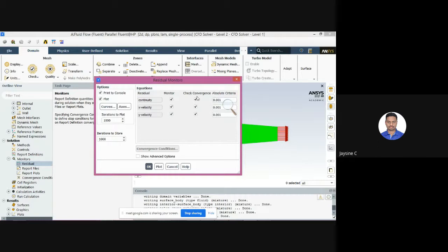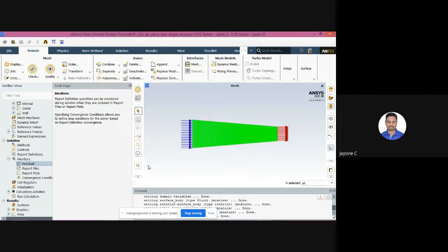This generally checks the convergence. So we're going to change this value. It should be as low as possible so that the problem will converge very fast, which means we will get a very accurate solution. So I'm taking 1e to the power of minus 14. Look at the value, how small a value I'm going to assign so that it converges fast. That is the residual we are given.